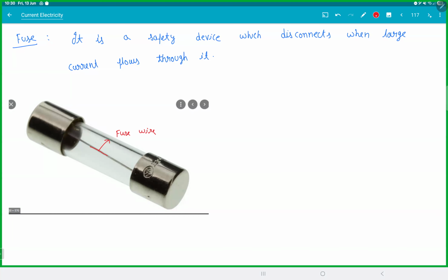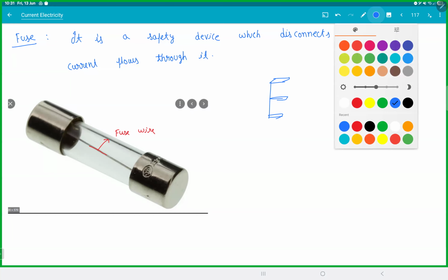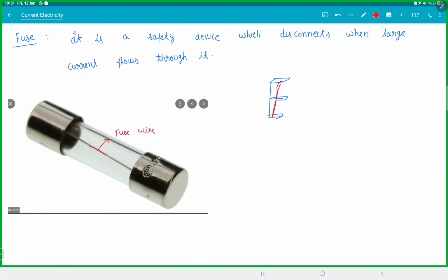People used to use this. Even I still remember when I was in school. Ever seen this thing? You have plugs like this. I don't know whether you have seen this. They still use this for big transformers. You have a big ceramic plug. You put that plug in, and these plugs actually have a wire passing like this. So this is your fuse wire. Anything happens, this gets disconnected. Once the wire burns down, you have to get a new fuse wire, connect it, and then put the plug back again. Then it starts working. So basically, this is a one-time use. Every time the fuse wire goes off, you have to buy a fuse wire and reconnect it again. So it was a headache.